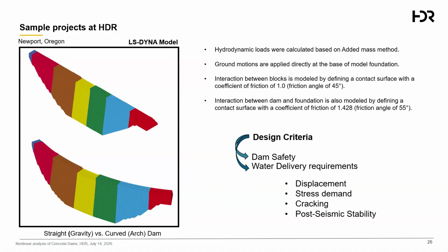As you can see here, for example, between the blue and red one, you can see a line. Actually, that's a surface, a plane between these two blocks, and as I mentioned, we call it contraction joints, and it's a potential plane for opening, for sliding, and for stress redistribution.